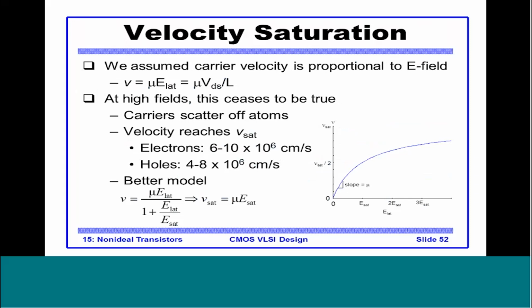In present transistors the L is of the order of nanometers. So let's say for a 40 nanometer device the L will be 40 nanometers. This is the reason why the drain voltage and the gate voltage have continued to reduce over technology shrinking, because the electric fields have been becoming so much stronger.